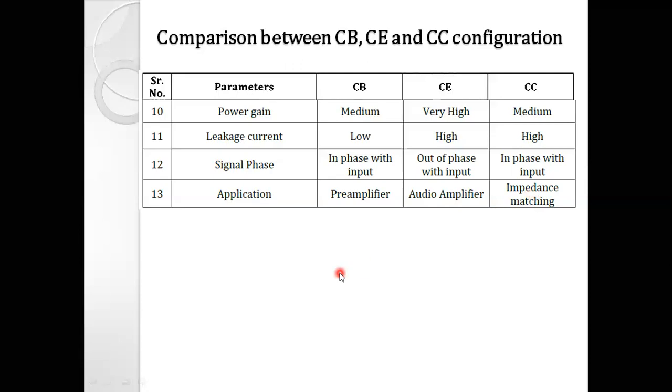When two or more circuits are interconnected, at that time we must ensure the impedance of one circuit should be matched to the impedance of another circuit. That means output impedance of the first circuit should match input impedance of the second circuit, so that we have the proper interconnection of the circuits, without any kind of interference getting propagated from one circuit to another circuit.